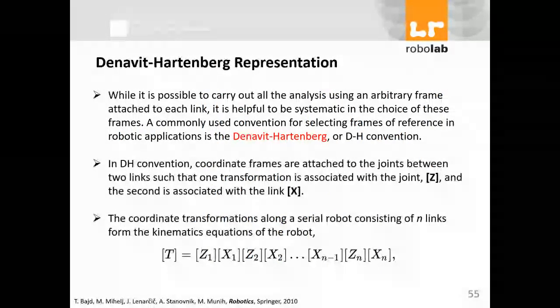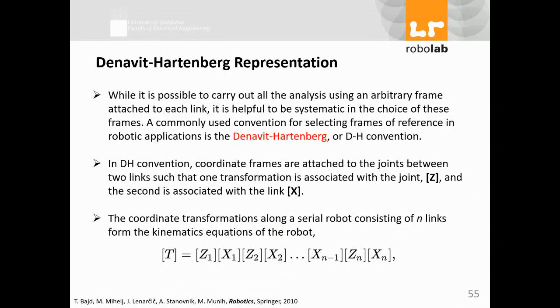And as I said, a general method for Denavit-Hartenberg representation, it says when I have a sequence of links, which we have in a robot. In a robot, when I have joint 1, joint 2 connected, and joint 3 connected together, what we do is try to build transformations based on two basic 3D movements: rotation and linear movement.